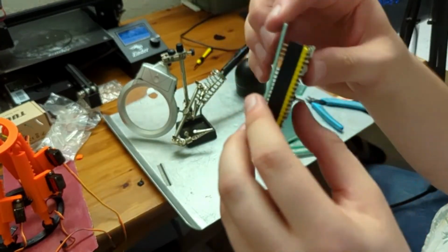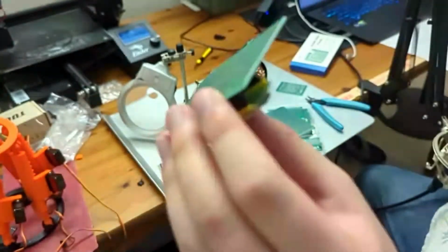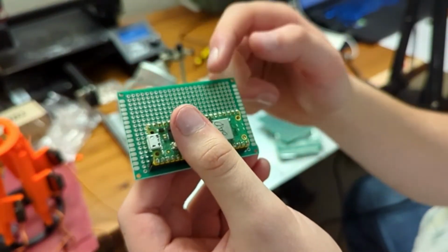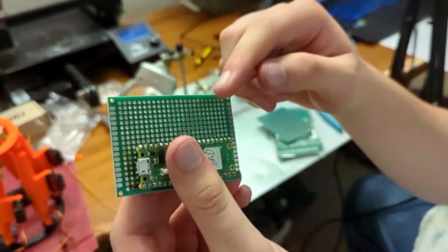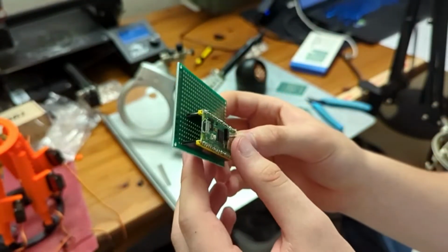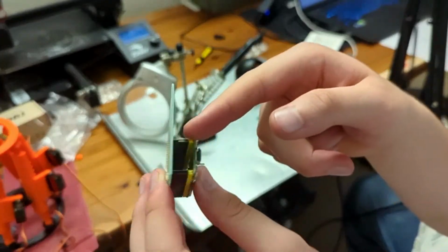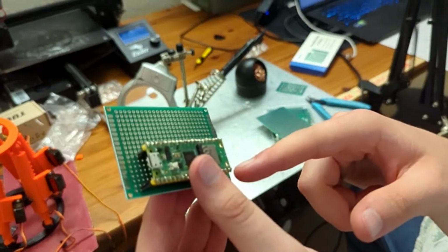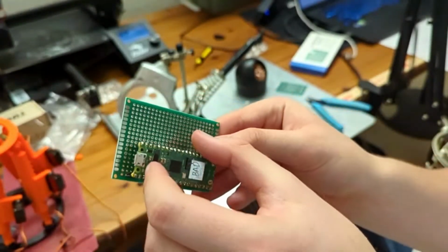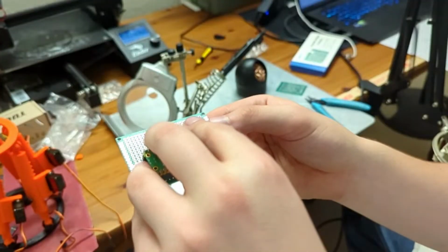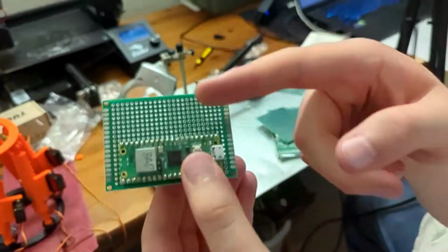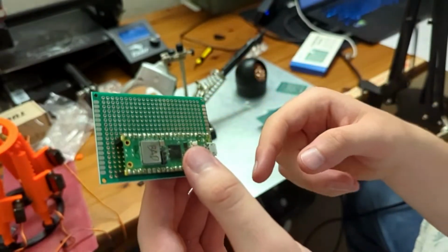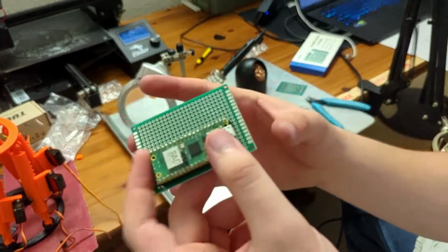Then with these Raspberry Pis, one of the things I'm thinking about is I need to maximize space on this side of the PCB for all the other electronics, but I also need a way and a space to run wires to the pins on this side of the Raspberry Pi. In fact, I'm almost thinking it would be better to do it this way, because so many of the pins we talked about using are on this side of the Raspberry Pi Pico. Yeah, this looks better to me.